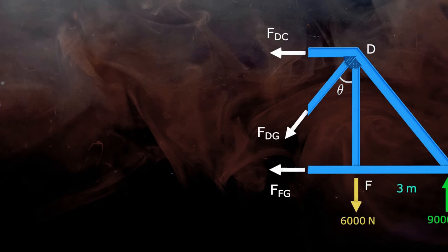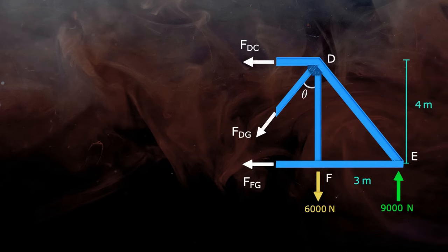Now let's get back to the force analysis. We know that we have 3 equilibrium conditions. First, we will solve for the condition sigma M equal to 0. To select the joint about which the moment is taken, out of the 3 unknown forces, select a joint where at least 2 of them are meeting.